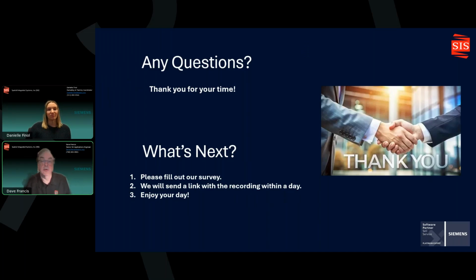Yeah, I think you could do that. You'd have to use an angle of 60 degrees around, and then you'd want a conical half angle to meet that flat face of the pyramid, which I think you could actually use a measure command to come up with a measurement and link it to. It'd be kind of interesting. There are probably other shapes besides a hexagonal pyramid, but something like that, I think you could use it for that.